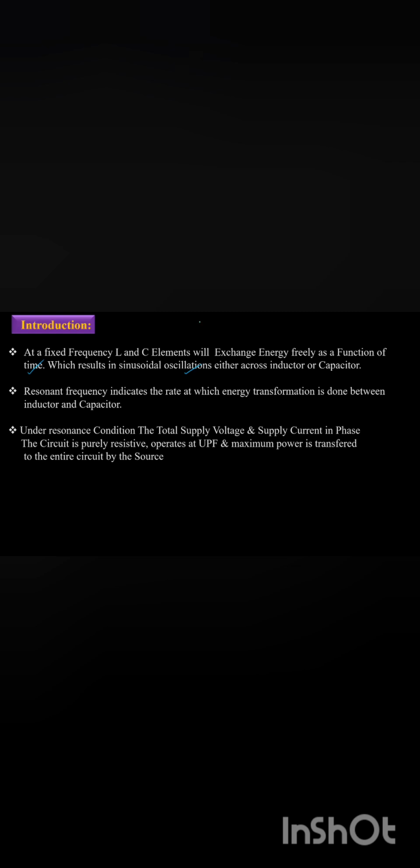Sorry, yes. At a fixed frequency, L and C elements will exchange energy freely as a function of time. During this exchange of energy from inductor to capacitor or capacitor to inductor, there exist sinusoidal oscillations across the inductor or capacitor. These sinusoidal oscillations have some frequency. If this oscillation frequency is equal to the system excitation frequency, then we can say that it is under resonance condition.